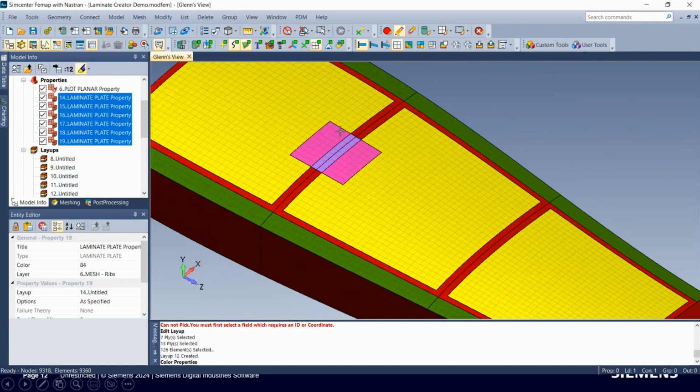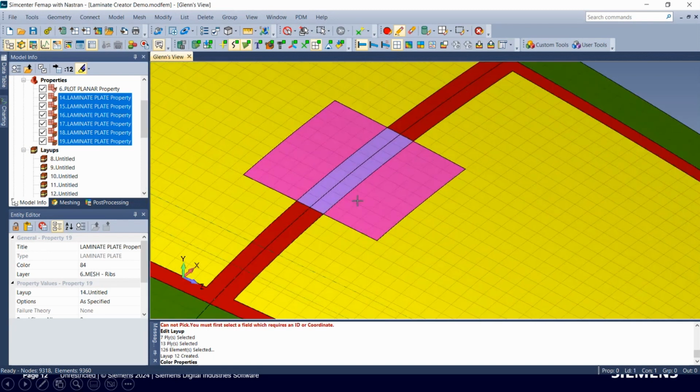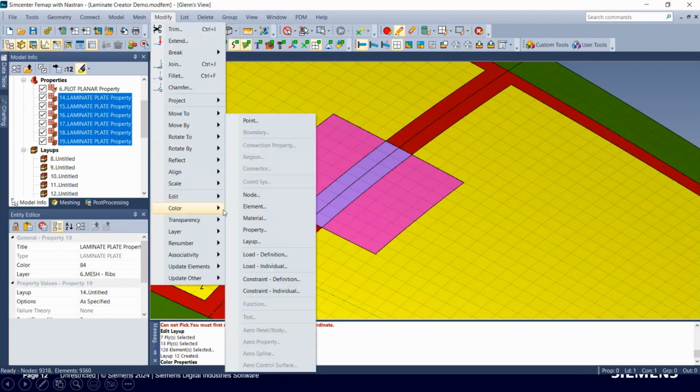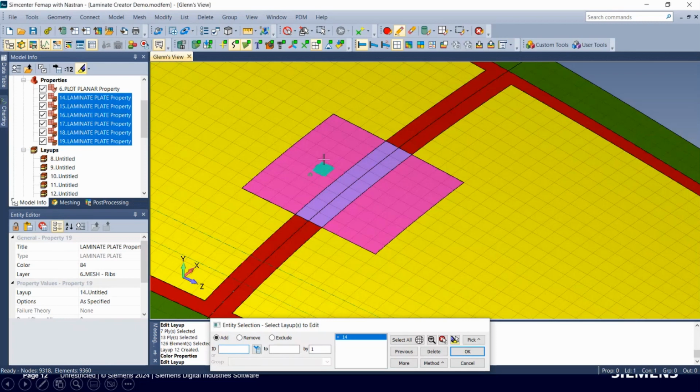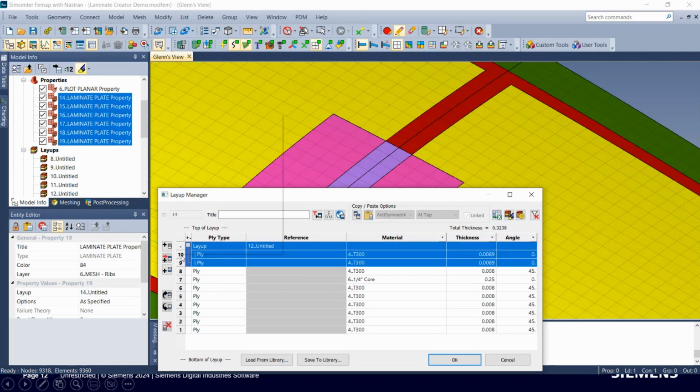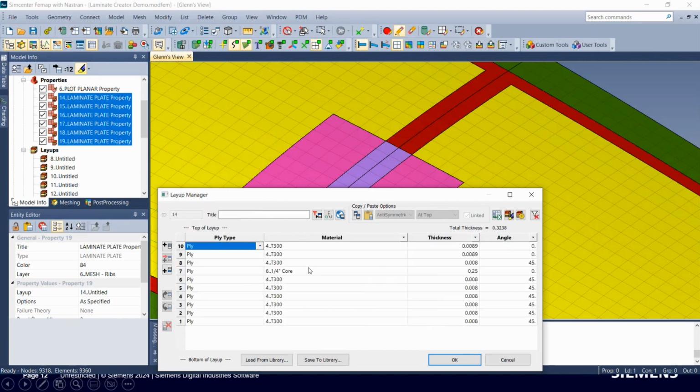And you can see I have 2 new properties defined, and we can go look to see what it's done here. So on the chord area, we've added 2 plies to the top of the layup, and it's actually in the form of a layup itself. So this is kind of helpful for showing like, hey, these are the actual 2 plies that were added by that function. And then if we wanted to get rid of this, we could just convert this to plies, and it would get rid of the layup stack and just make them plies on their own.